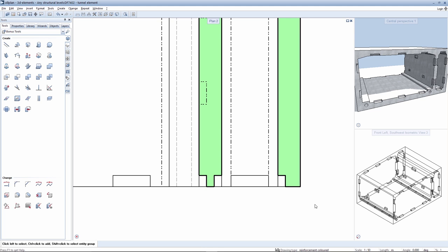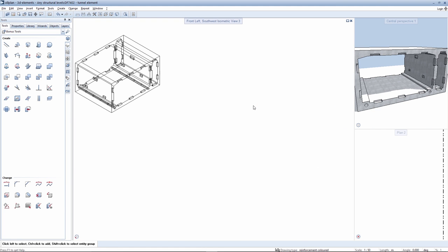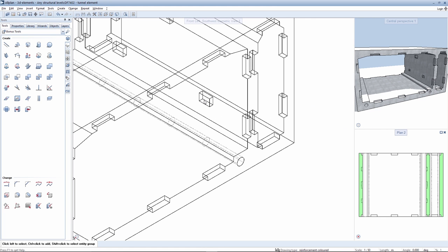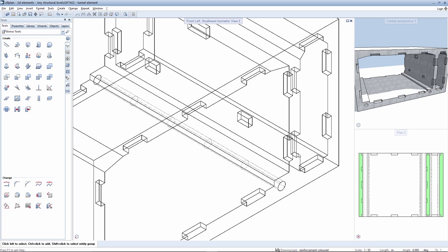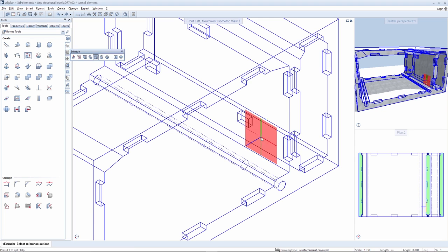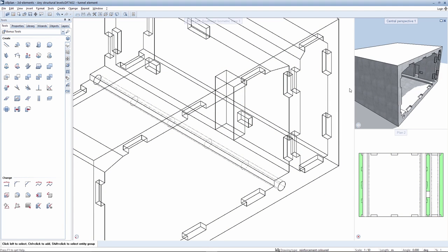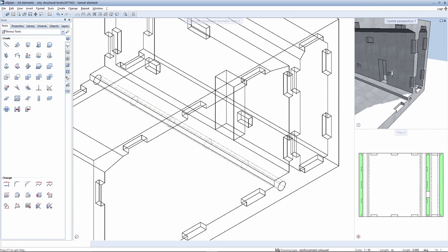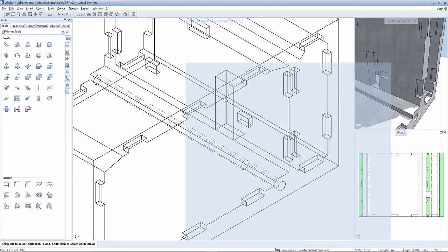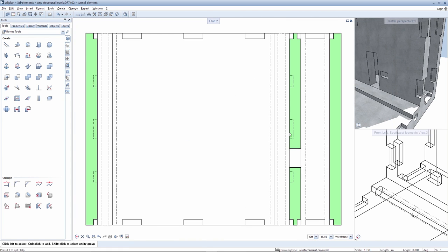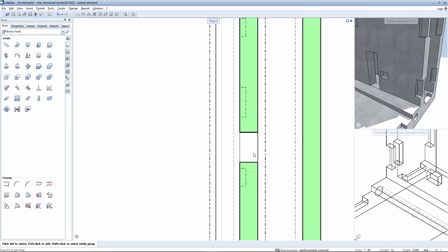Naturally enough, further modeling of user-defined architectural elements of this kind is possible if you use the modeling tools for 3D modeling in the relevant perspective. An opening is integrated here in the partition wall using the extrude function. The ground plan of the user-defined architectural element adapts according to the depiction of the opening.